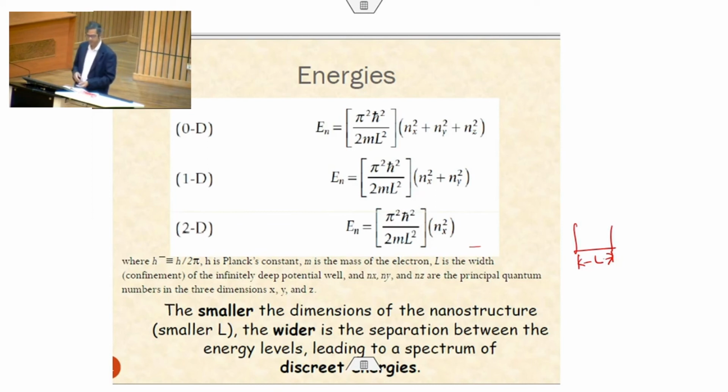So, in bulk homogeneous solid materials, the wavelengths of the phonons and of the electrons will be much, much smaller than the length of the microstructure. Let's talk about microstructure, because the length of the material may be different, but the grain structure, the microstructure, is what is very important. So, in a homogeneous bulk material, the wavelengths of phonons or electrons will not make any difference at all, because the length of the microstructure is much, much bigger than the wavelengths.